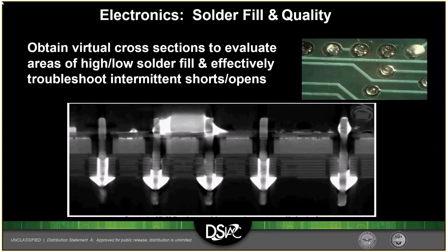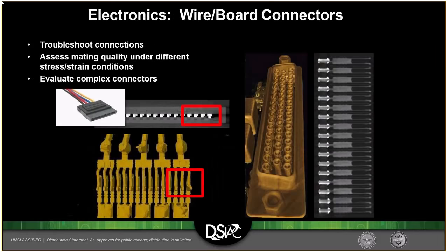You can go through and measure the shape of the solder ball, detect any voiding. You can see the head-on pillow defects. There's a lot of tools you can use by cross-sectioning at all these different angles with the CT scan. X-ray can tell you if you have a void or a misshapen BGA, CT can actually model that for you and show you what that looks like in 3 dimensions.